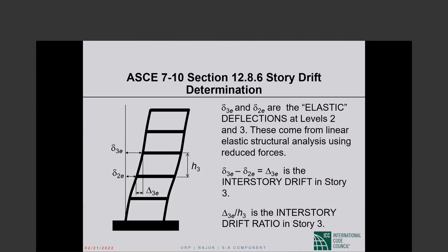Building separation provisions changed rather significantly from ASCE 7-05 to ASCE 7-10. ASCE 7-05 really did not have specific building separation provisions. It was kind of an in-principle provision like in BNBC. ASCE 7-10 has specific building separation provisions, which I think are important. So in this segment, I have gone to ASCE 7-10 definitely for the building separation part. The rest of it is ASCE 7-05 or 7-10, there is really no difference between the two. Some slides have ASCE 7-10 in the title, some have 7-05, but again, other than building separation, there is no difference between the two.